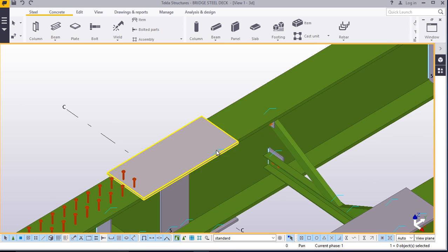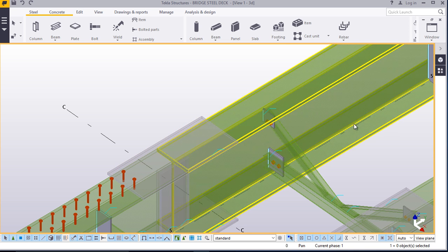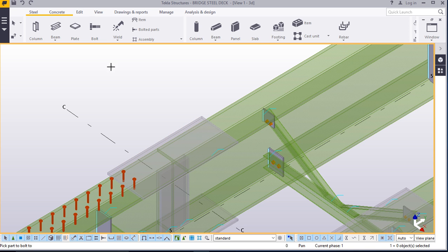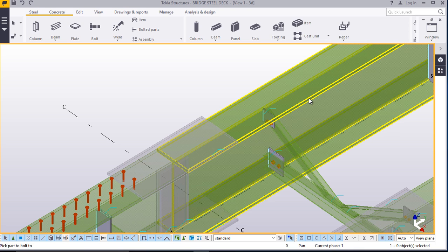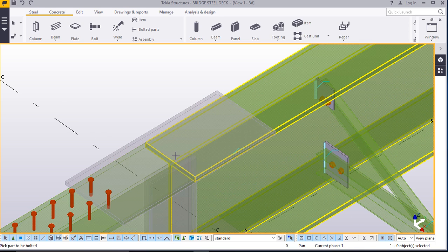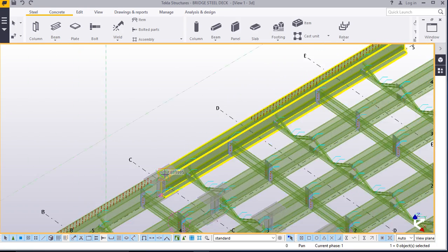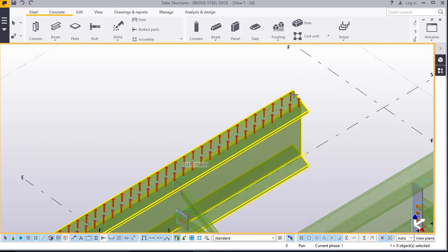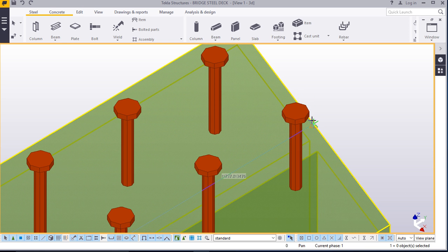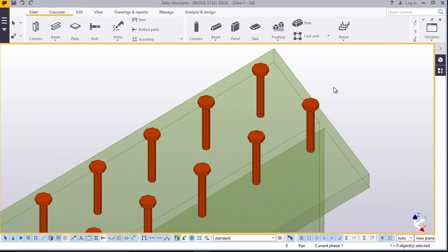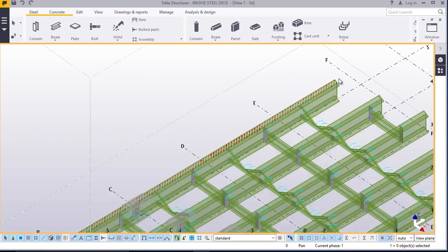We have a space here remaining, quite simple to place. Press Ctrl 2. Come to bolts. Click that, press spacebar, snap in the middle point of that. Snap there, right click and interrupt.